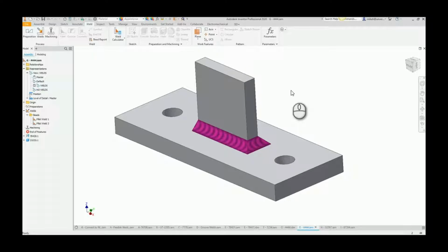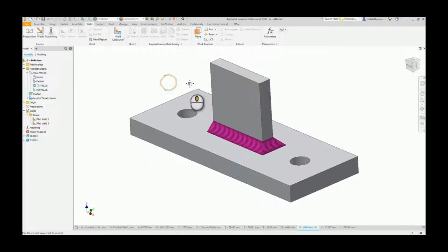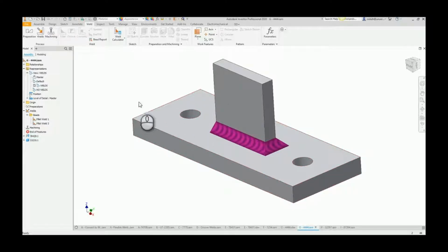It's pretty much out of the box white from Inventor. And then we also create one that's the welds, or the annotation, and that is just this pink magenta color. But in this welds view representation, we do show the welds, and we also do show the weld annotations. We don't have any here yet, but we will get into creating those.